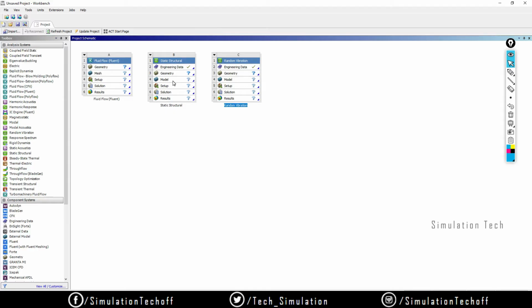Likewise, Fluent also has some steps. First you design the geometry, then create the boundary conditions, and assign the initial velocity and pressure, like this. Once we solve a simple problem, you will know that you want to do this at the first stage and then move on to the next step. Following along, you will get the pattern. Okay, I will delete these systems, we don't need them anymore.